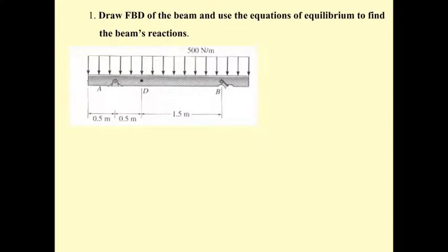Okay, if we understand that, we can draw the free body diagram of the beam correctly, taking the beam out of the support under the action of the forces. You may set the reference x and y axes here, and then A sub x is going to be in the x direction, A sub y in the y direction, and the force in BC along its axis. So the angle here is going to be 45 degrees.